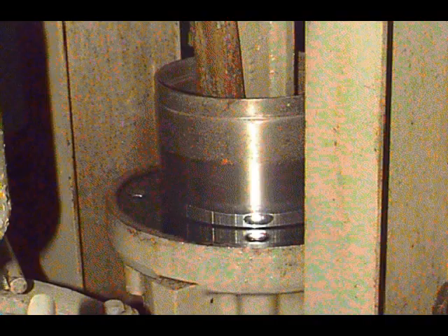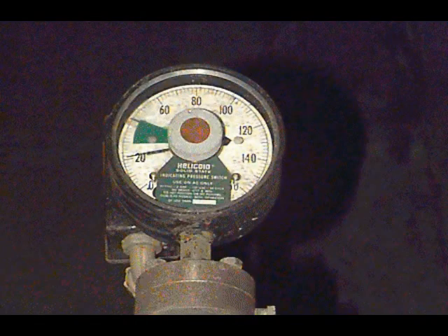Gauges and pressure relief devices are two other important components of the plunger and piston positive displacement pump systems. In discussing these two components, keep in mind that these pumps are often used to pump sludge. While the positive displacement type of pump does not clog easily because the back and forth movement of the piston or plunger tends to break up potential blockages, some problems still arise. Let's consider the gauges first.